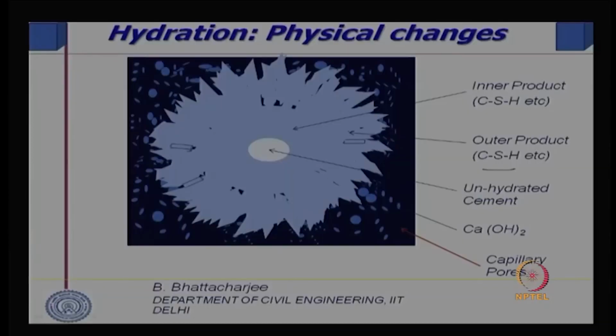surrounded by water. Now, as we have seen, when these solids touch each other at some corner, the solid skeleton is formed, and from the other side another particle touches, and so on. But remember, there will be a large quantity of pores remaining at the initial stage, unless you have very little water, less space to be filled by the solid products of hydration, and the continuous reaction progresses over a long period of time. We will look into this in some more detail later on.